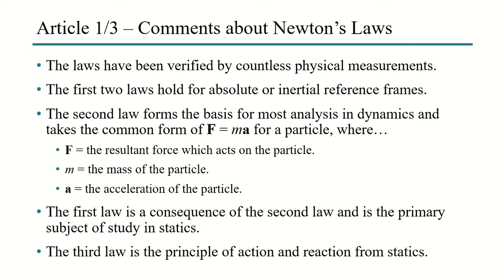The second law forms the basis for most analysis in dynamics and takes the common form of F equal to the product of the mass and the acceleration for a particle, F = ma, where F is the resultant force which acts on the particle, m is the mass of the particle, and a is the acceleration of the particle.